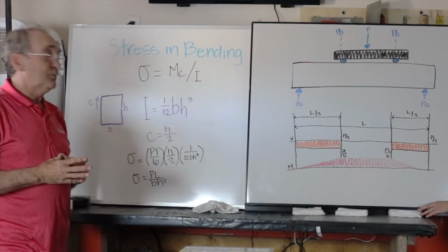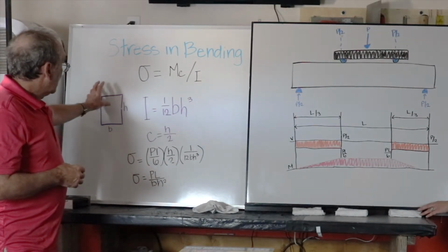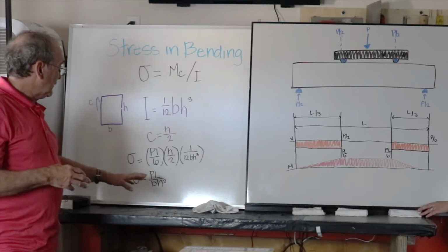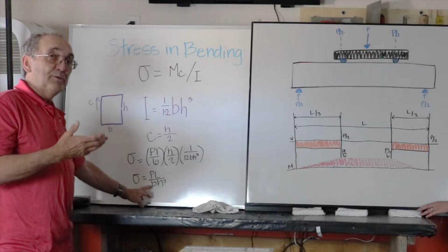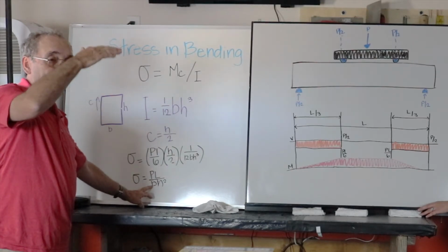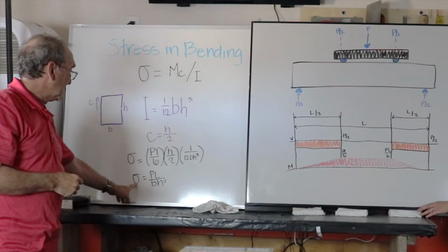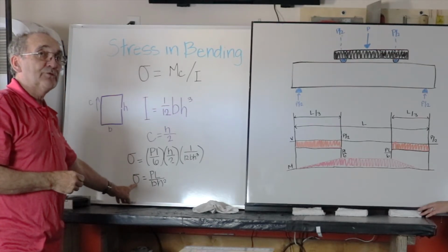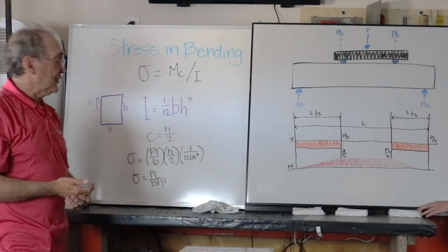Why on earth did the committee decide to do that? Well, they decided from the theory of elasticity that this may not be the perfect expression for stress in the outside fiber. It may be that the stress comes down and then tapers off a little bit towards the edge. So they decided to name this the modulus of rupture to distinguish it from confusion of being the direct tension test in the outside fiber.